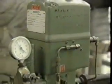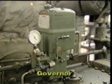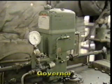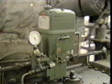Turbines are also variable speed drivers that use governors to keep their speed constant and control the amount of steam or gas that's supplied to the turbine during operation. Turbine speed is measured by a control mechanism that actuates a throttle valve to increase or decrease the supply of steam or gas to the turbine.